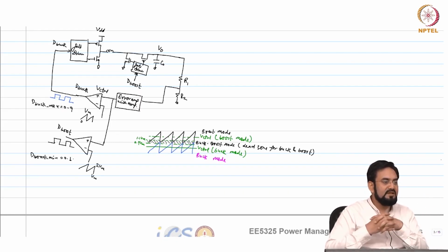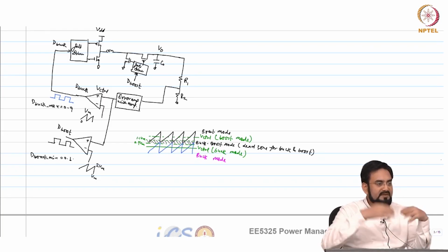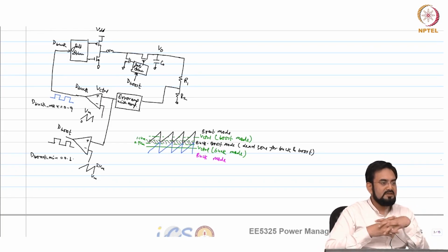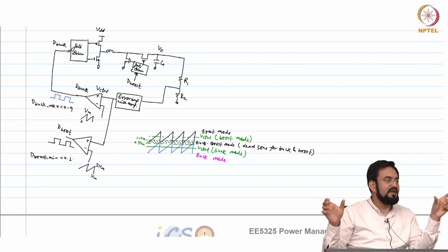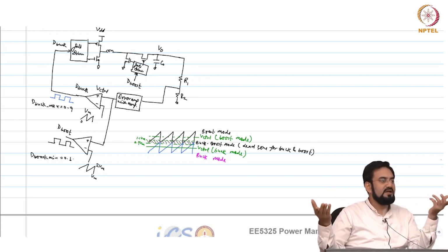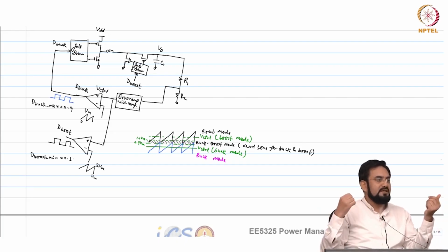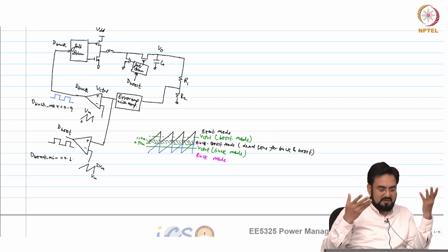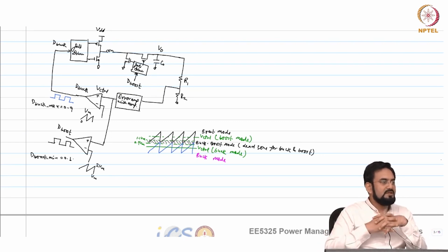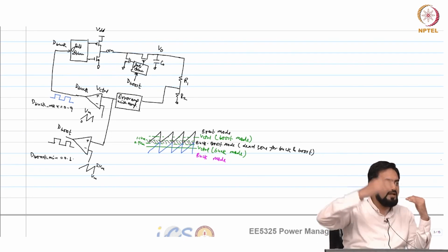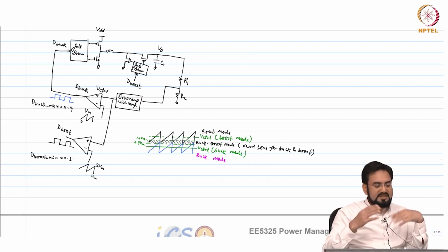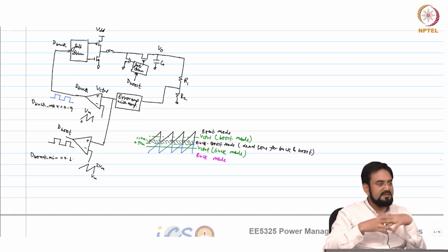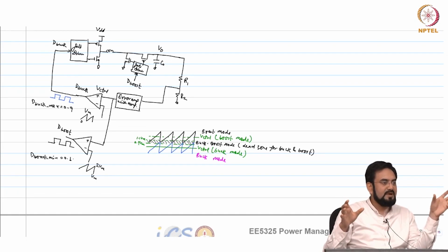Yeah, use pulse skip mode. You dither between 2 duty cycles. So let us say 1 buck, 1 boost. So let us say I give a 0.9 buck and 0.1 boost. This is equivalent to what? 100% duty cycle. Okay. Now if I give, let us say 4 bucks and 1 boost, so that will be less than 100%, between 0.9 and, okay. So that is how you do. Basically you dither between 2 duty cycles and choose the number of cycles of buck and boost.